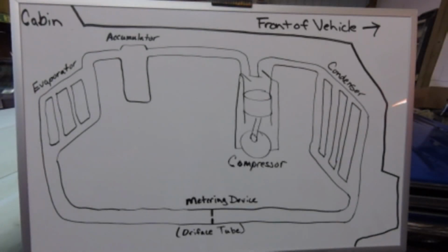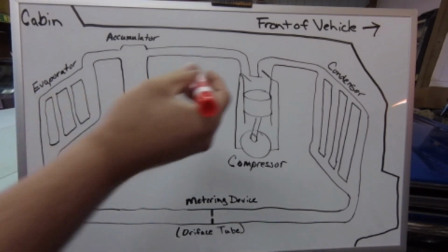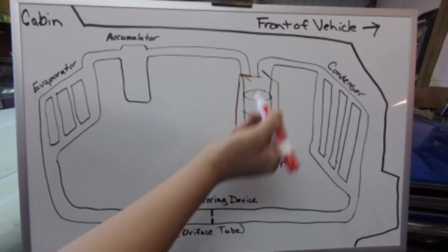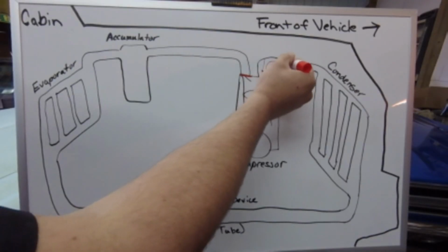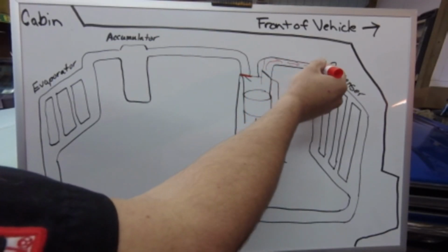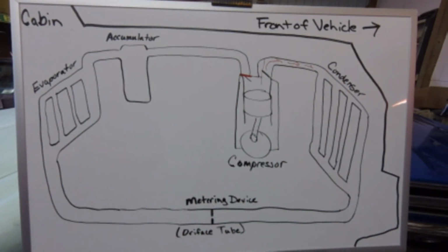The refrigerant cycle begins at the compressor, where low pressure vapor refrigerant coming from the evaporator is now squeezed in the compressor and pushed against the metering device, building high pressure in the system. It is a vapor. Any liquid getting in the compressor would be catastrophic because liquids do not compress compared to vapors, which can be compressed.